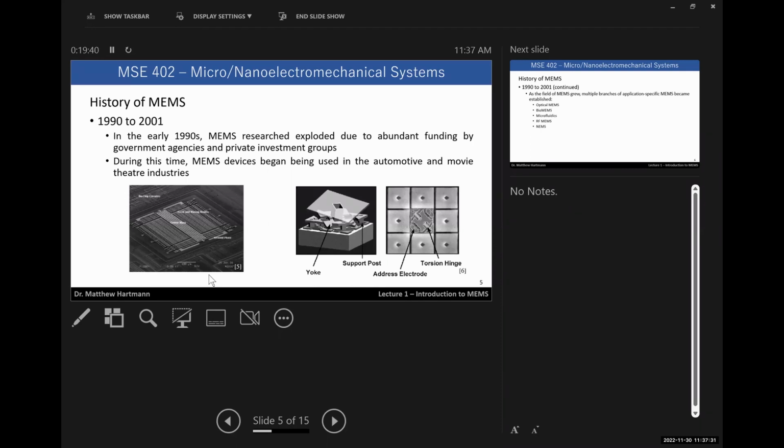So these TI micro mirror devices are really super neat because it is an integration of a mechanical device, the mirror array and all that kind of stuff. It utilizes electrostatic actuation to deflect the mirror positive 12 degrees and negative 12 degrees, and it sits on top of a CMOS memory cell. Okay. Each individual mirror has its own memory cell associated with it. If the memory cell has a 1 in it, the micro mirror is deflected positive 12 degrees, causing light to reflect off of it.